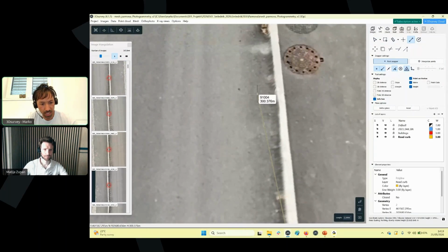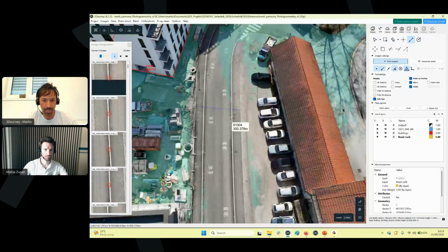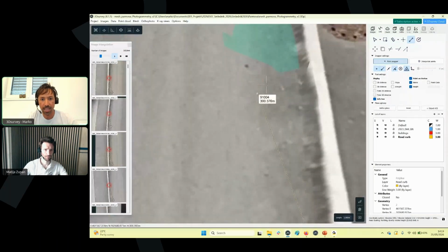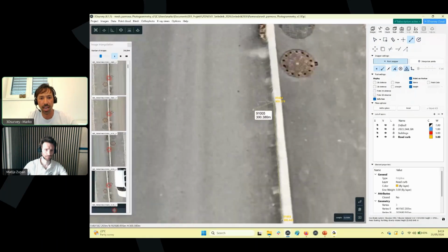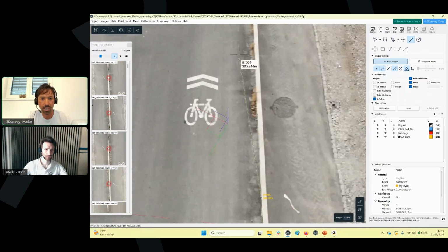As soon as I press the Q button and hold it, the software creates a quick plane for me, as you can see. And I hold my Q button and I position my mouse at the location where I would like to have the point and line. So Q, left mouse click. Press Q, hold it, press left mouse click.